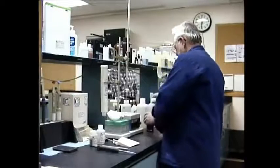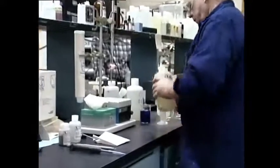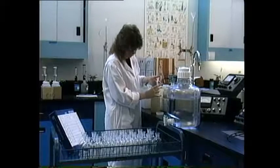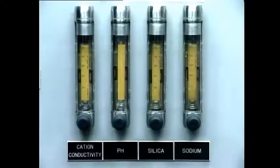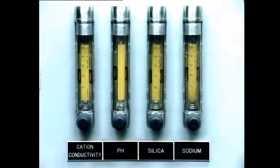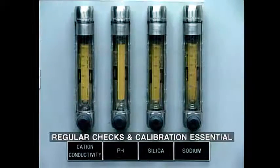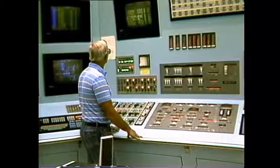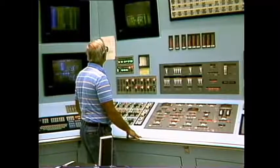Most large power plants are equipped with specialized personnel and lab equipment to perform boiler water analysis and control. In smaller industrial plants, the operator may be required to carry out certain tests with backup from a visiting specialist. In many plants, continuous automatic analysis is performed and displayed on a panel. Of course, in order for the readings to be meaningful, it's essential that the equipment be regularly checked and calibrated. The operator must always be aware of the actual boiler water conditions at any time and how this compares with the established limits of operation.